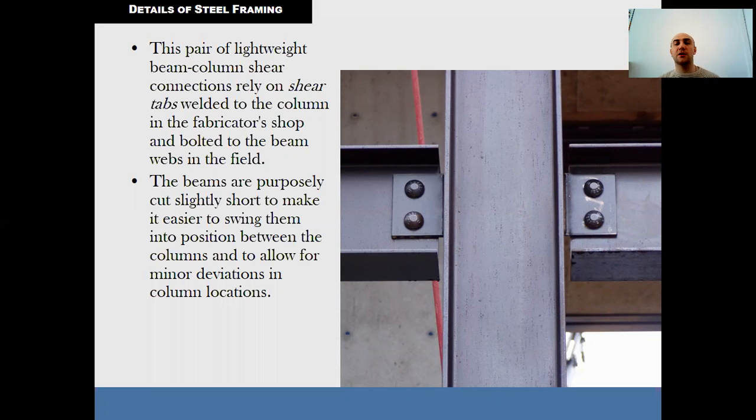The most common configuration of angle connection is that both sides of the connection are bolted, and using bolts reduces the cost. A single connection creates somewhat less rigidity than a double connection.